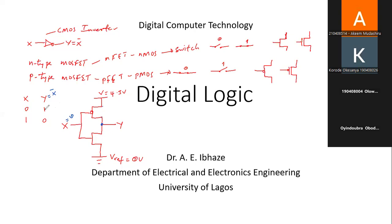So we're expected to get our output Y to be 1. But looking at the model, the P-type, when we feed it with a 0, turns into a short circuit. So this is what we're going to get. Our voltage here is 4.5 volts. So this now is going to be replaced with a short circuit, right? And then we have our Y here.